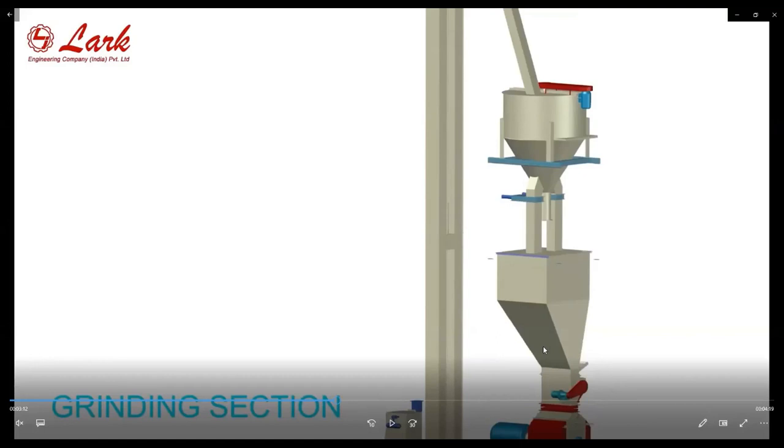The grain and heavy density material provide inertia to the light material to pass through the screen, and the grains help the fibers in the grinding process. Also, when the grain comes, the load on the hammer mill increases, and when the fiber comes, the load decreases. There may be a pulsating load with respect to the grain hardness.